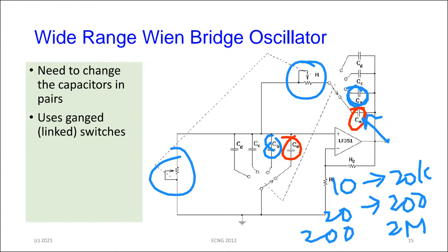You're not going to get much higher than that using these components, because the higher the frequency you go, the smaller the capacitors you have to use. You then run into that limit that you would have learned about the op-amp, the gain bandwidth product. So as the bandwidth increases, the gain drops, and there's an upper limit to this performance as well.